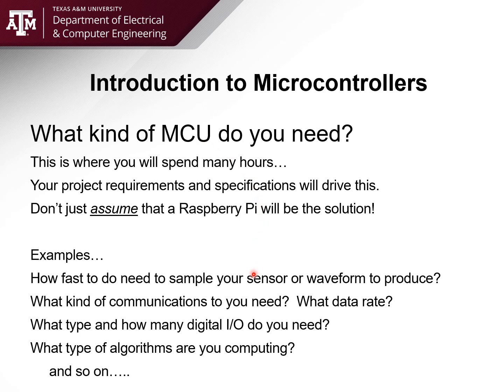And how you communicate that camera data to the microcontroller also matters. So there's a lot of things that have to be taken into account there. How fast are you going to communicate? If I only need to send occasional data here and there, like settings and user input, that's one thing. If I need to move data, like I was talking about the images, back and forth between the microcontroller and, say, a database somewhere, in that case, you probably are going to need megabits per second or maybe even gigabits. So what are you doing there? How many digital I/O do you need? This all comes down to, in the end, coming up with your requirements and specifications.